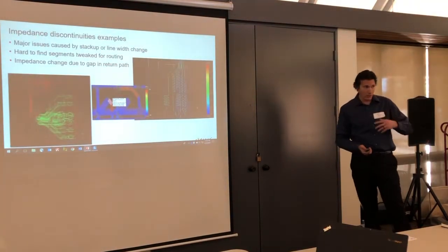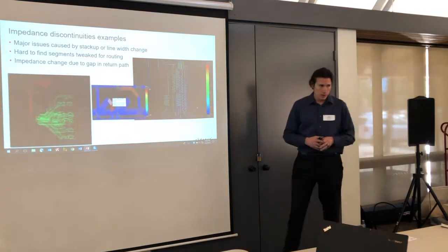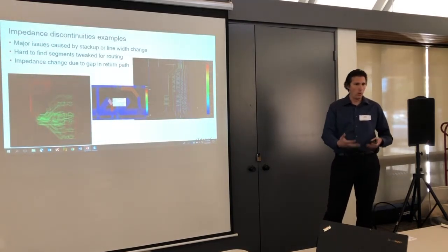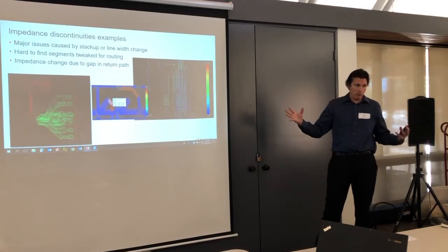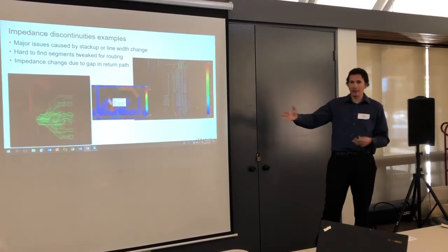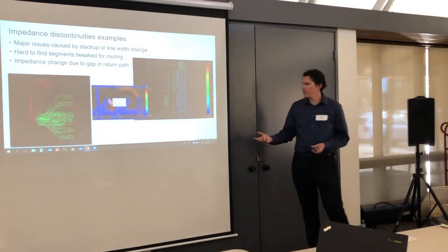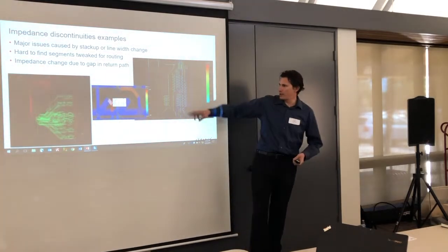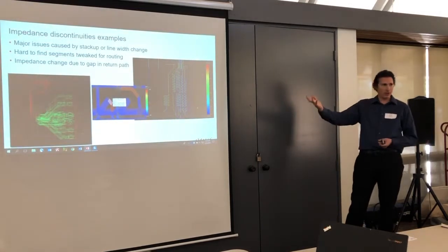I would recommend taking a look at the tools all over the market that can analyze things like this for you. You may have a design where everything was great, and then all of a sudden the fabricator comes back and says, your dielectrics have changed a little bit, or swap these layers in your stack up, or get rid of these layers, or add an extra ground plane layer. You may want to quickly know, everything was perfect before in my impedance world, how badly did that break it? Do I have a whole bunch of nets now where the impedances are completely violated? Or you might have routed everything perfectly, but had 1 or 2 cases in the design where you had to trim down a segment just to get it in there, and now you have a small segment of etch that has a different impedance than the rest of it. Is that going to cause a problem?